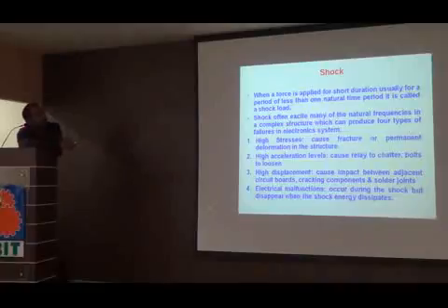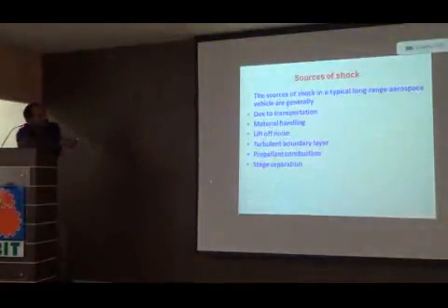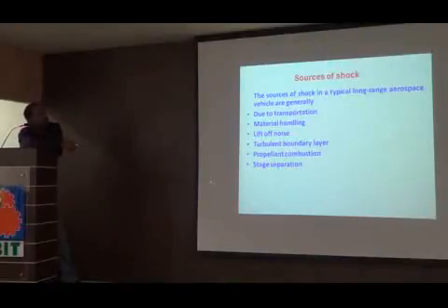When a force is applied for a short duration, less than the natural period of the system, then it is called shock. In our system, we get shock due to transportation, material handling, and lift-off noise. This includes the turbulent boundary layer, meaning the flow is not in a viscous manner but in a turbulent manner, as well as propellant combustion and stage operation.